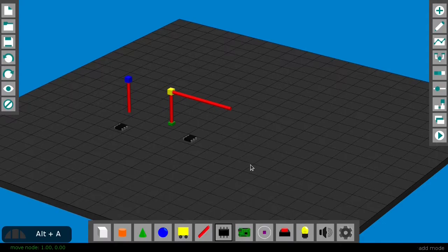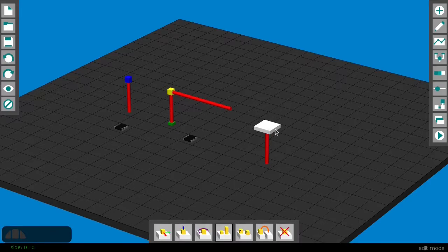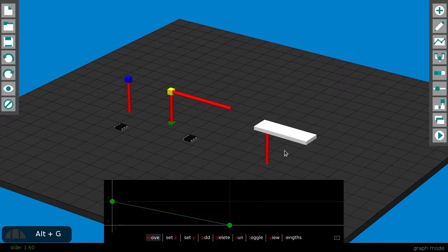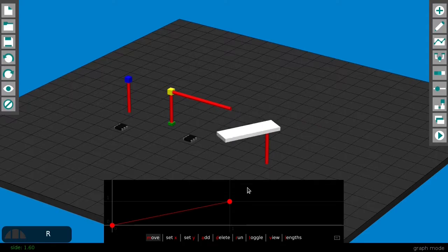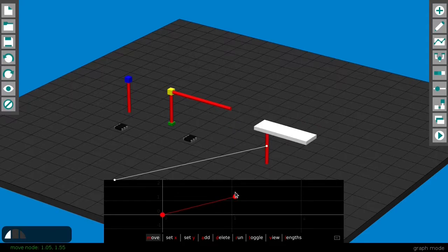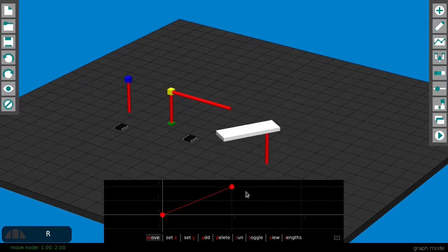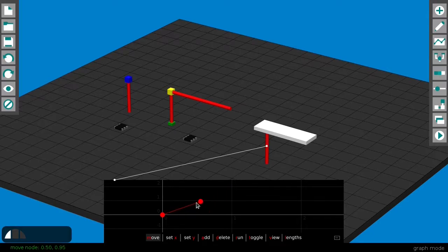There is also a different kind of motion, rotation, and it's created with a track. Add a track like this and add a block to the top. Or click anywhere, it's the same as adding to the top. Now scale the block into a blade. On graph mode, add the track to the graph. The value of the track is its angle from 0 to 1, 1 being 360 degrees. If you want it to rotate twice in 1 second, make it move from 0 to 2, or 720 degrees. If you wanted it to move halfway, wait for a second, then move back, you would do this.